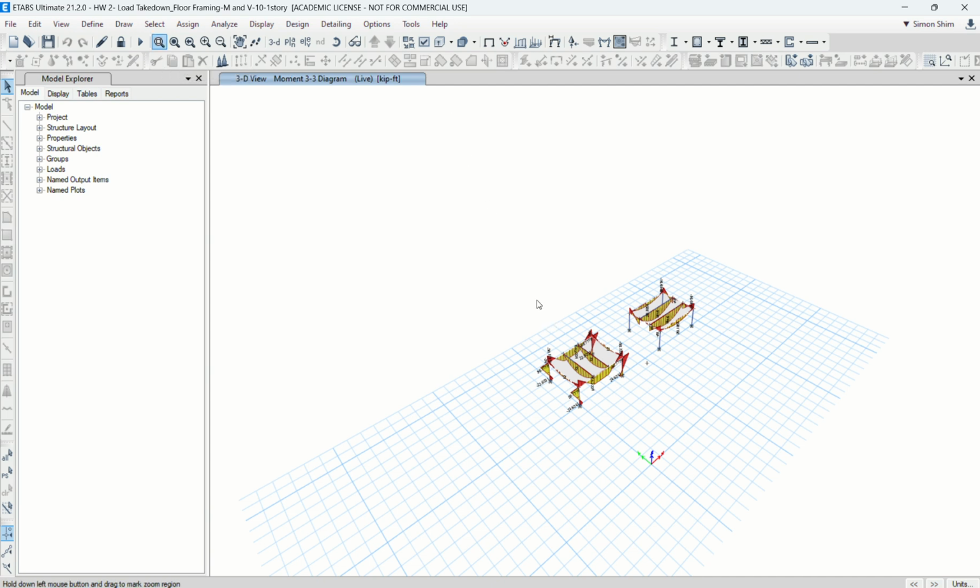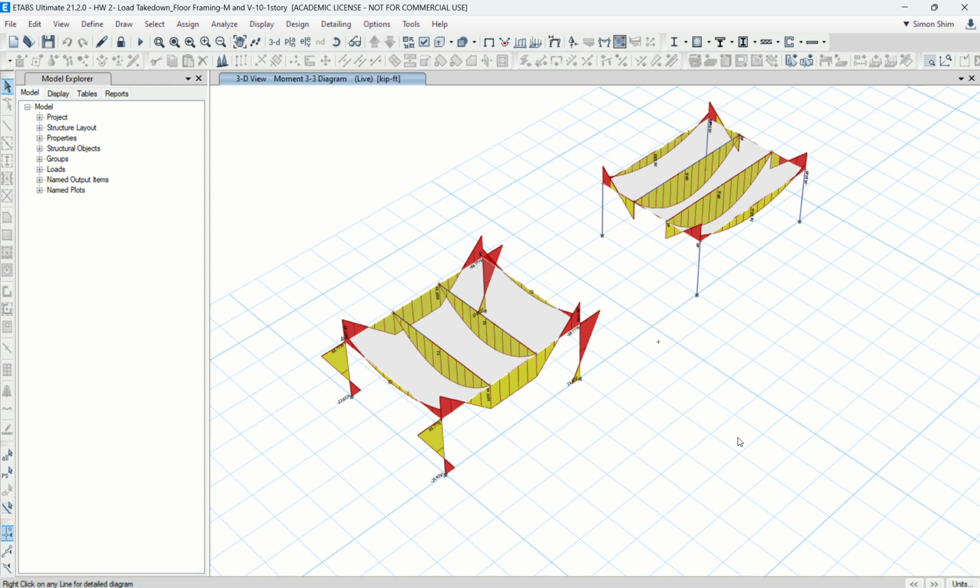Maybe I'll share one thing, and this is because it's a 3D structure. When you run it, you also need to understand elastic stability. Otherwise, ETABS is going to give you an instability error or warning message, because we build the model in 3D, right? We follow X, Y, Z coordinates. We build this 3D structure, right? Vertical loading is all the way down, typically no issue, but when we build it, ETABS internally analyzes it and checks whether this building is stable or not.